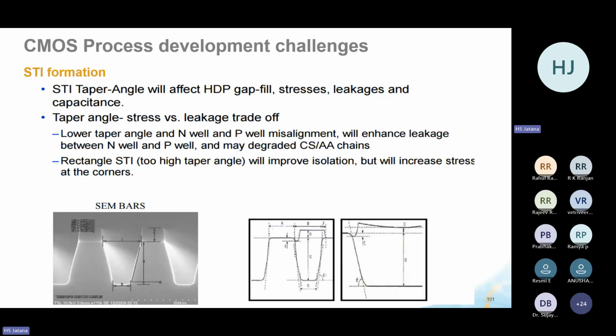So these are the things in an STI that you have to make. Now the unit process: for the process engineer, the first process will be the etching. He has to etch that area and create this trench of a particular dimension with a divot like this. This divot will be created afterwards, when we deposit the high-density dielectric on that. At that time it will be created.